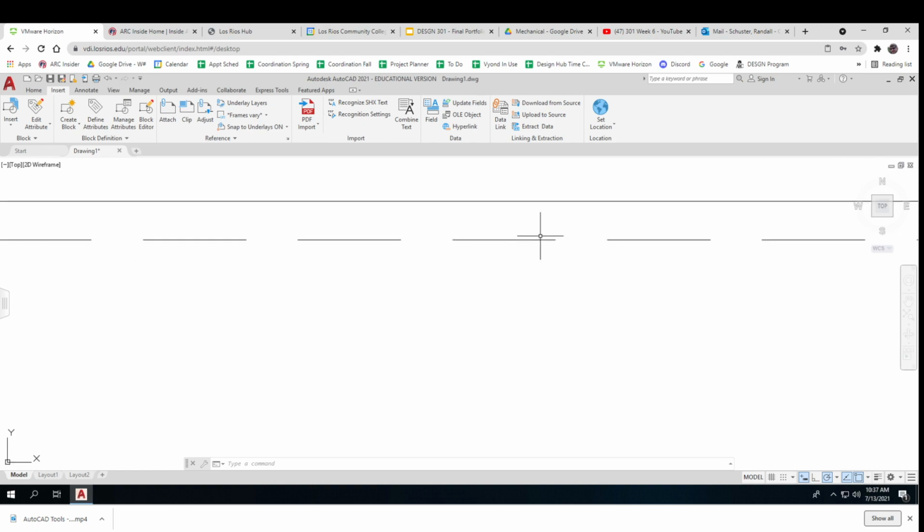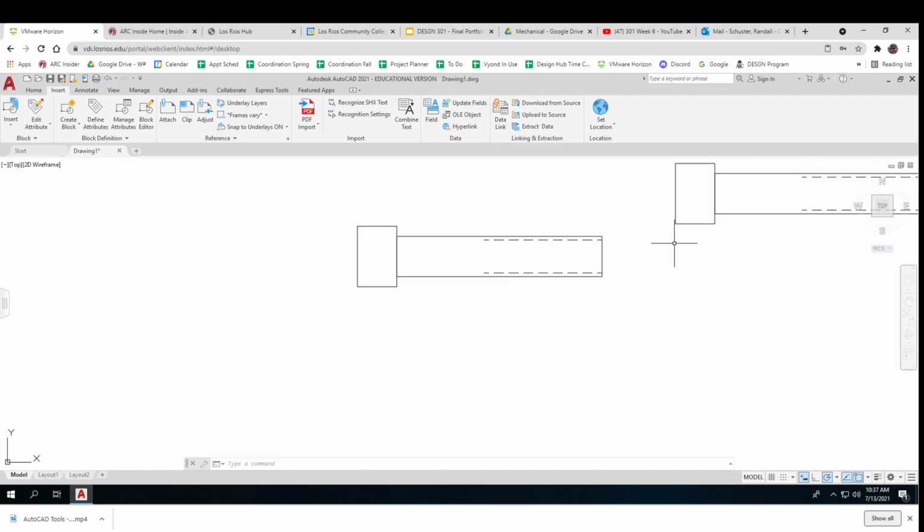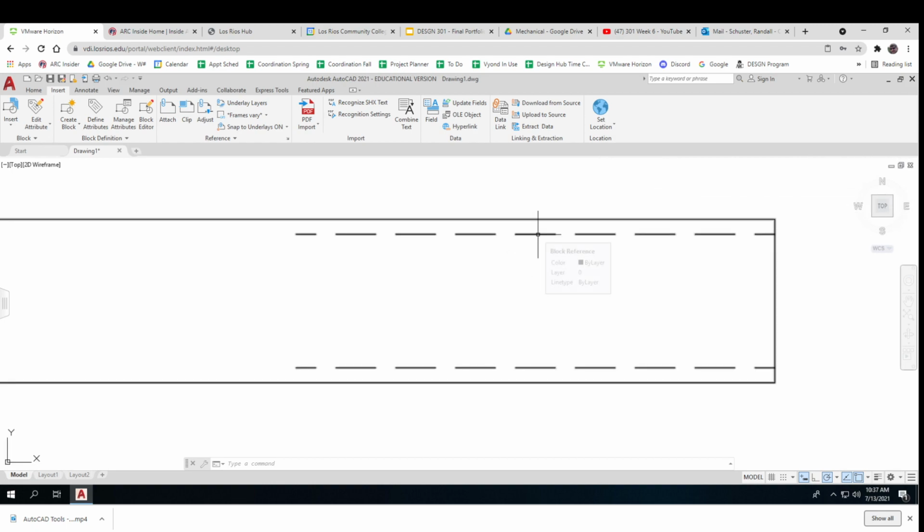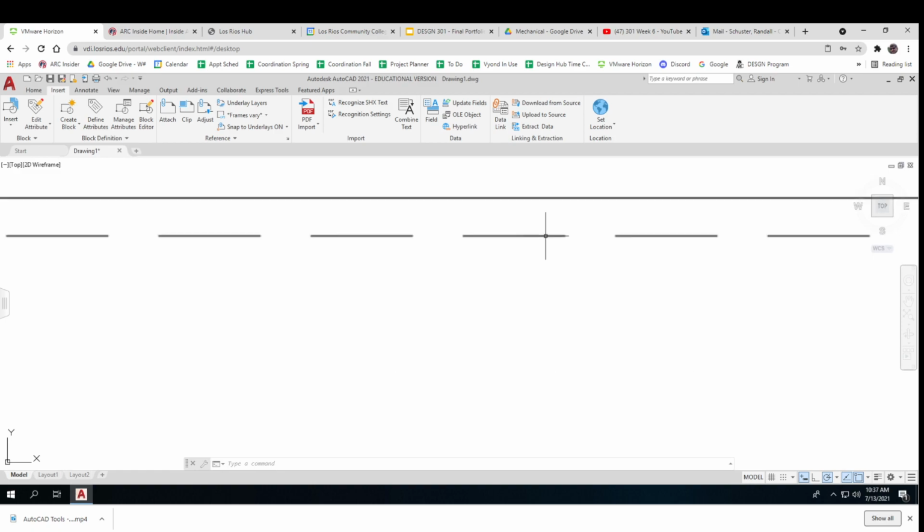Now we did have to put our minor diameters or our pitch diameters in because we did do overlays. And if our pitch diameters didn't match up, that's how they were looking for whether we had a loose fit or a standard fit or a force fit. They were looking for where these little lines overlaid, and we had to draw within a 64th of an inch.